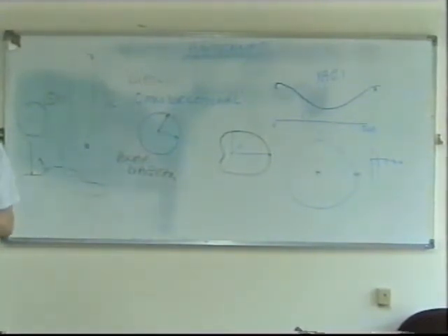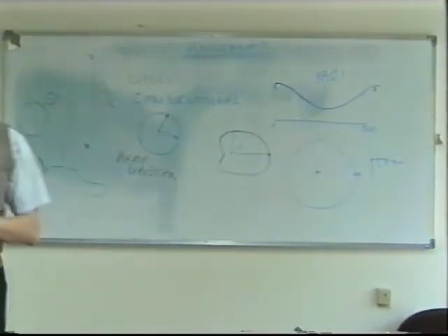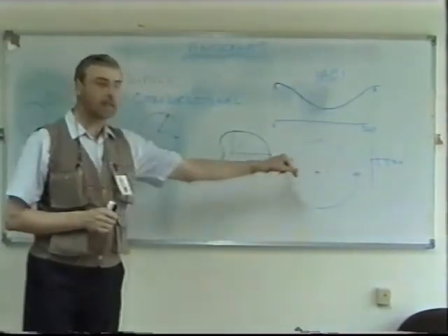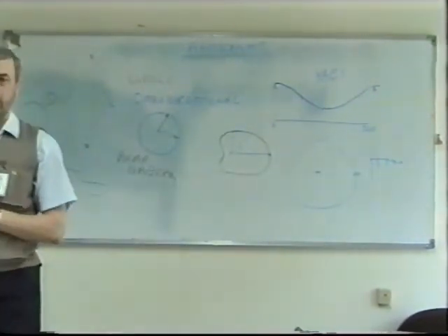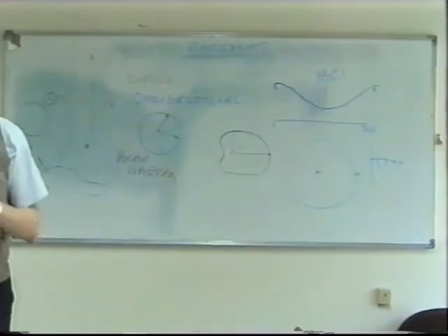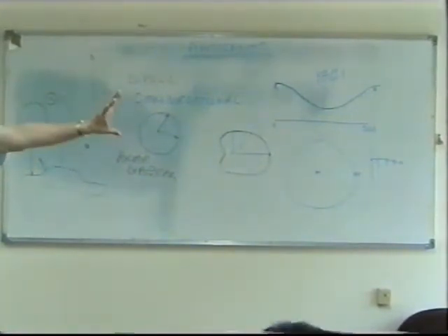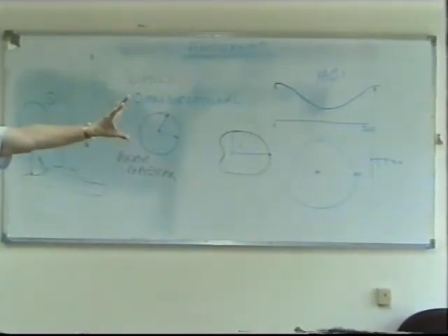Yeah. In theory, no. In practice, maybe. But that depends on how direct. For a Yagi, I would say no. I think he would still be able to hear it, but it would be very weak. And the weaker the signal, the more it's going to be affected by noise. Remember, in any communication medium, whether you're talking about a cable or radio, you're going to get noise added to your signal at the receiver.